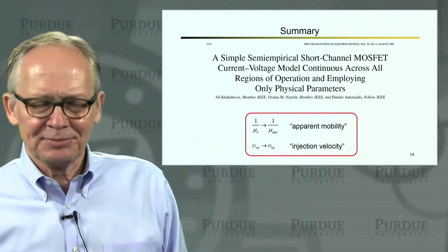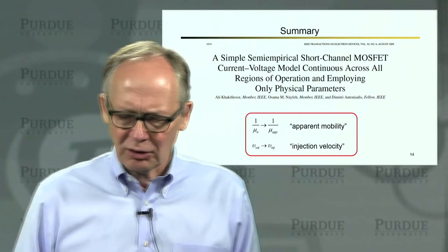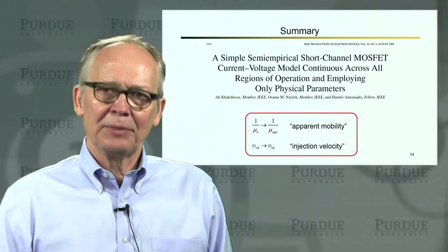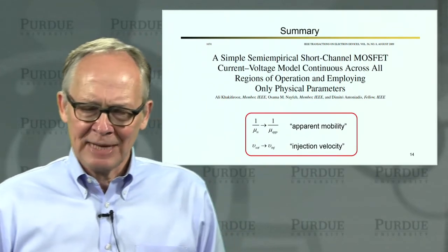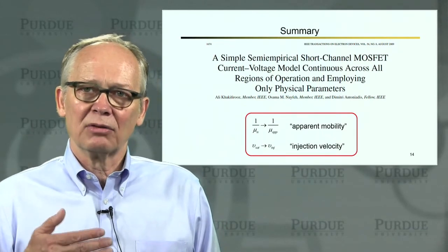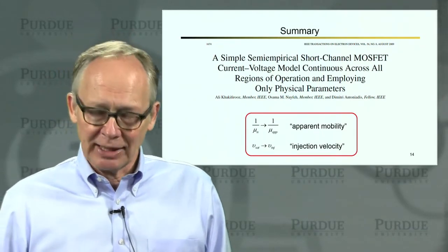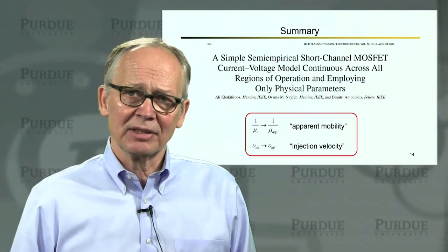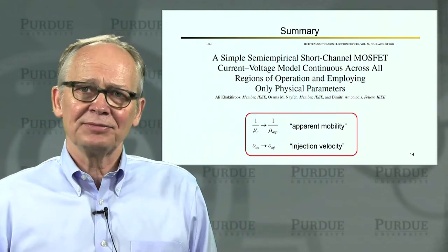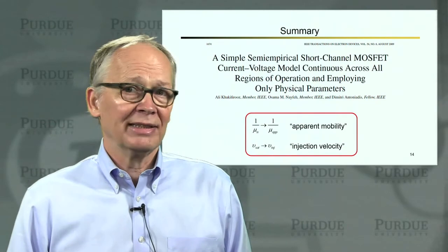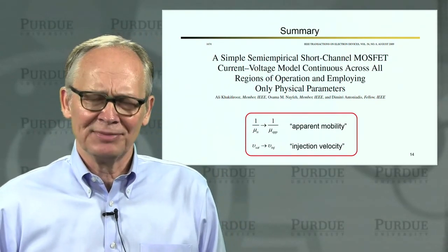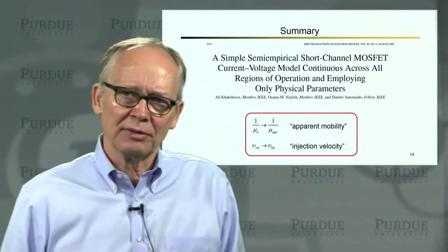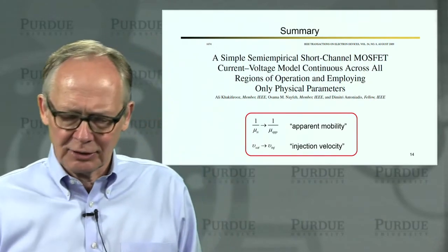Now, the thing that is a little bit mysterious here is you'll recall that when we derived this model, we used very traditional concepts of semiconductor physics and electron transport. Concepts that are well-founded when we have long channel lengths, a micron long, 10 microns long, when the theory was first developed. What we saw when we looked at the detailed simulations is that there are some very serious issues with the physics in that problem. For example, there is no high field velocity saturation. And we're not sure what mobility means when we get to very short channel lengths. That's a concept that is well defined for large bulk chunks of silicon.